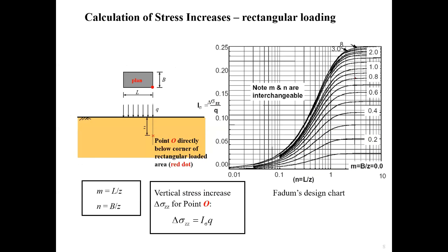So by now we have learned the point load and also the circular loading. But in real scenarios, many loading situations occurring in practice consist of a number of rectangular regions. So actually this part is really important. We have to be careful about the rectangular loading. It is of interest to be able to calculate the vertical stress increase due to uniformly distributed load acting on a rectangular loaded area. This is shown schematically in this figure.